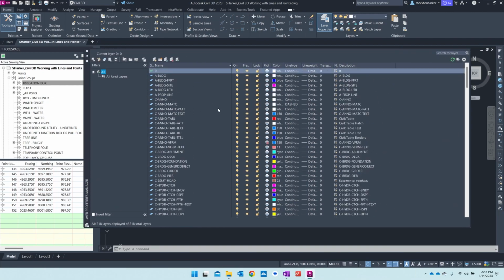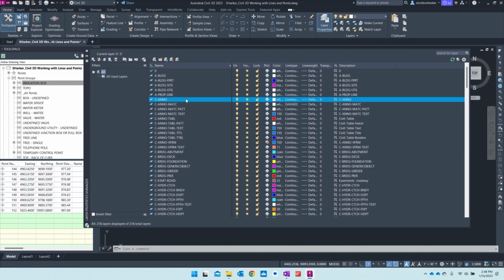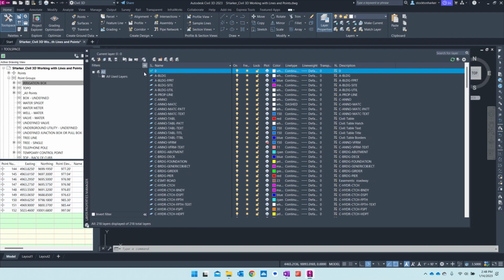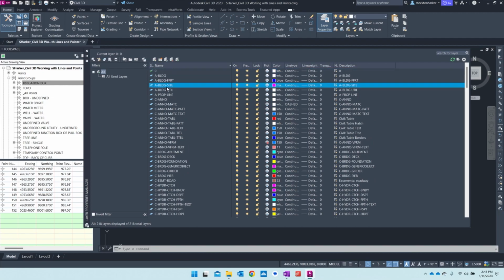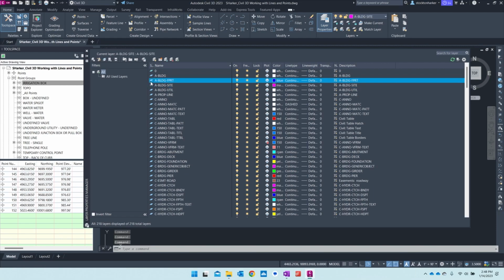The way that a layer works is you can draw something on that particular layer and then you can turn that layer on and off. Just imagine it as pieces of paper that you're taking on and off the desk. But these pieces of paper are transparent and you're drawing on top of them. So for example, layer 0 is the default layer, and it's the layer that is currently selected. You can tell which layer is the current layer by the green check mark next to it. It's called the active layer. This is important to note because you cannot freeze the active layer, and the active layer is the layer that you are currently drawing on.